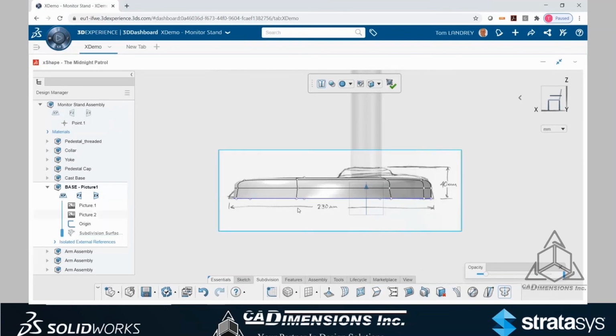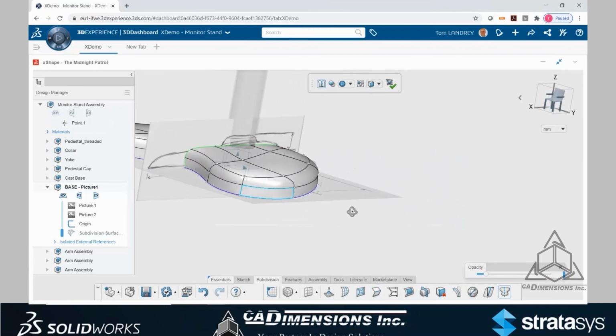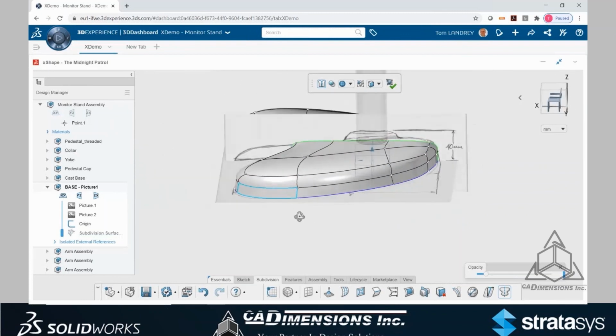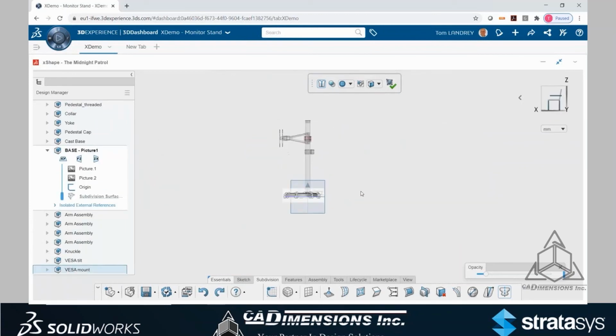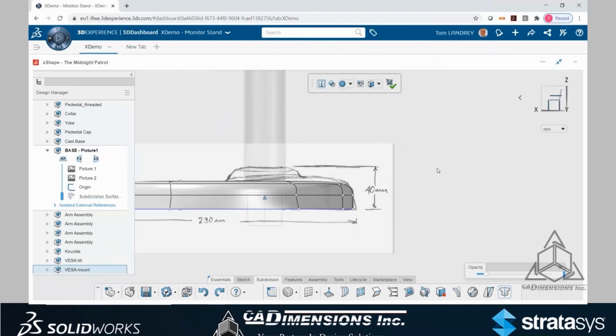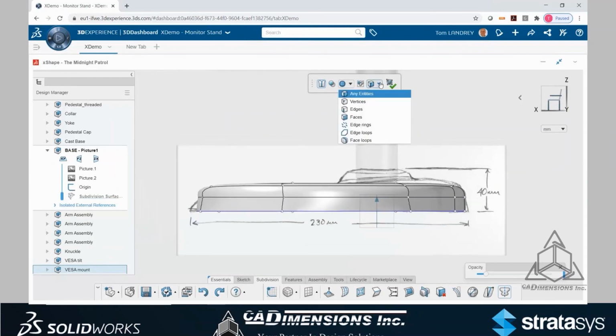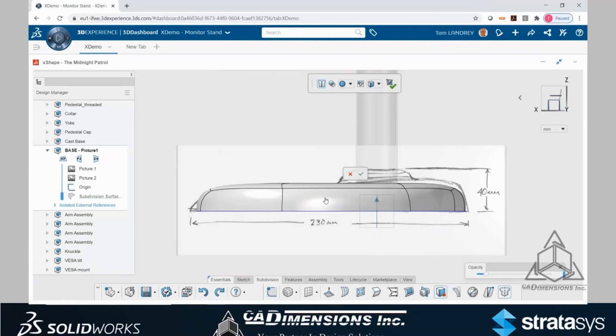Now, a couple things you got to do, and whenever you learn anything new, you got to make sure you hit the right buttons. One of the things when I did the crease, I had to tell it I'm done. This program is modal, very similar to how SolidWorks is modal. It's doing things till you tell it not to. So I'm going to go back to all entities so I'm not picking just the faces. I'm going to pick edges and everything like that. I'm just going to grab this one edge and hit the delete key. When I originally put the shape together, I gave it too much information, and I don't need that. So I'm simplifying it. Just like any surface modeling, you want the least amount of nodes you possibly can have. It's the same thing here.